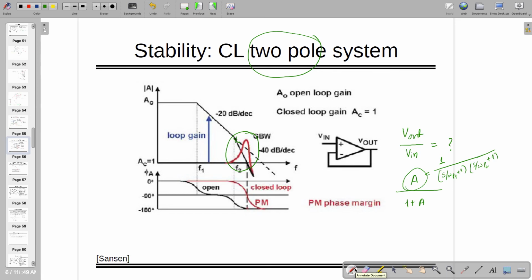One more time, what do you say? What do you think triggers the response? Okay, this one. Can we infer that the leakage is from the second stage? Leakage. What do you mean by leakage? Because our gain is gradually increasing. That way it is reaching the output. You are saying the closed loop gain or open loop gain? In this configuration, V out by V in has to be 1, right? But what if this is a second order system and the second pole is inside? That is what I'm asking.